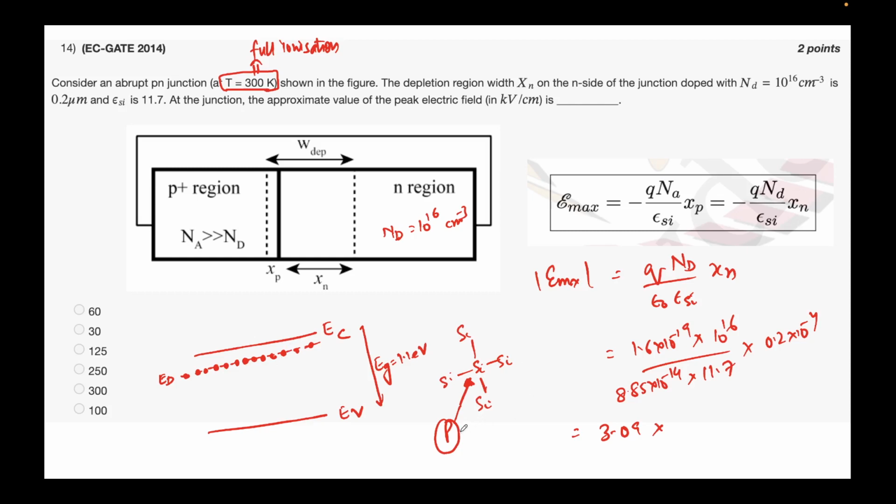An electron is bound to phosphorus, mind you. It can become free if someone gives it some energy, and that energy is provided by the temperature. At room temperature, the extra electron that phosphorus has can become free, so a lot of these electrons can jump here. Now you will say silicon also has electrons here. Yes, definitely, much more than phosphorus. In fact, this phosphorus doping is 10 to the power 15 or 16. Here you have 10 to the power 22 electrons, but this gap is so large.